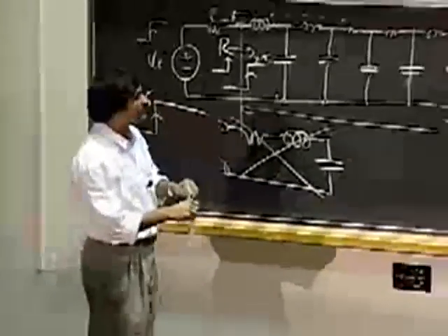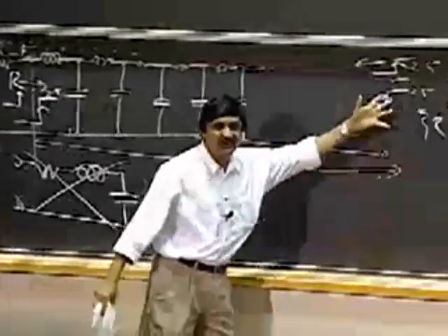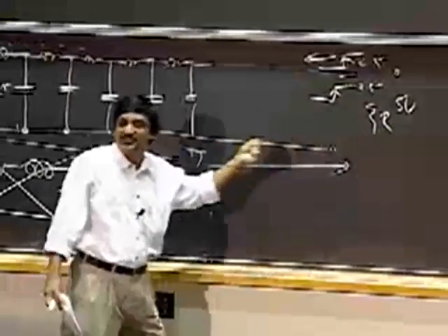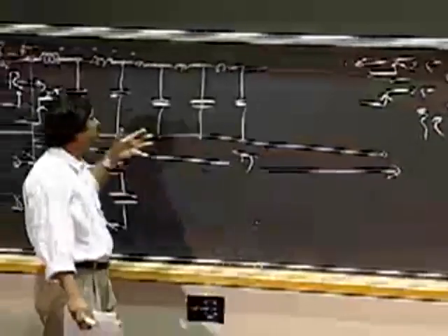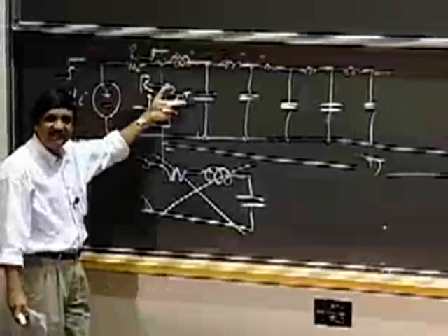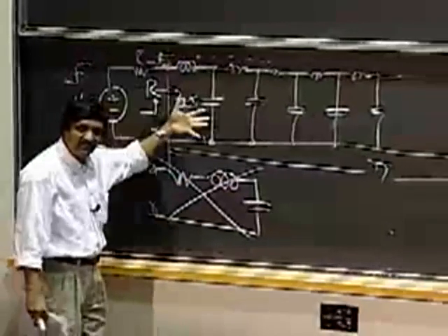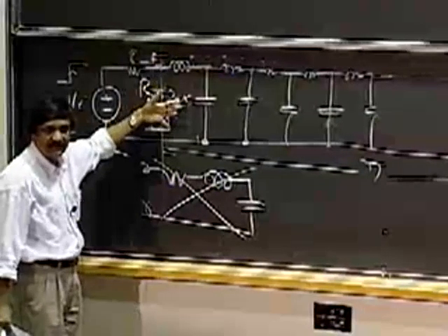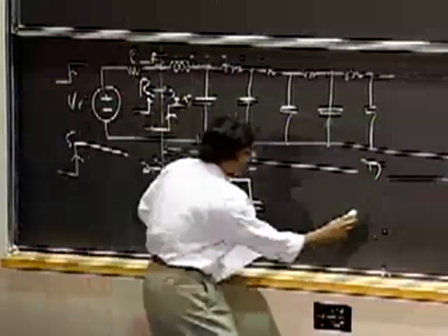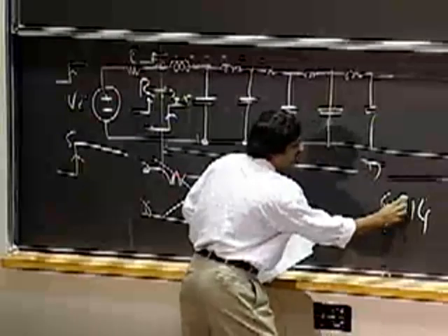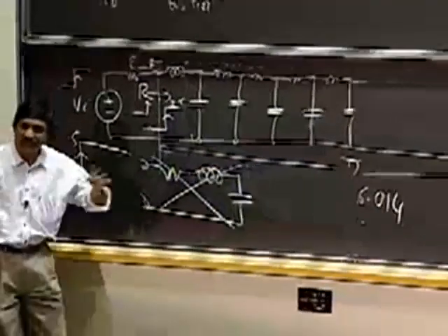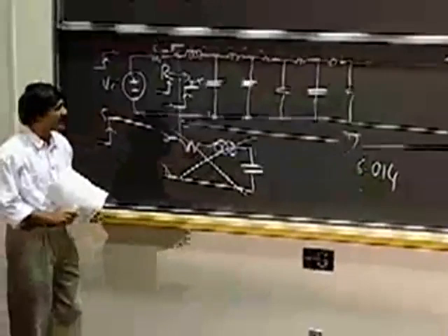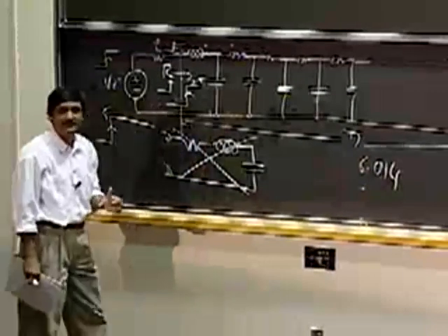So that's one solution. One solution is to put a resistor here, so I absorb the energy, and the resistance has to be equal to the instantaneous impedance looking in. That instantaneous impedance, for many of these cables, is 50 ohms. It's called a characteristic impedance. You'll learn a lot more about it if you take 6014. That course starts out assuming that things are distributed in that manner.